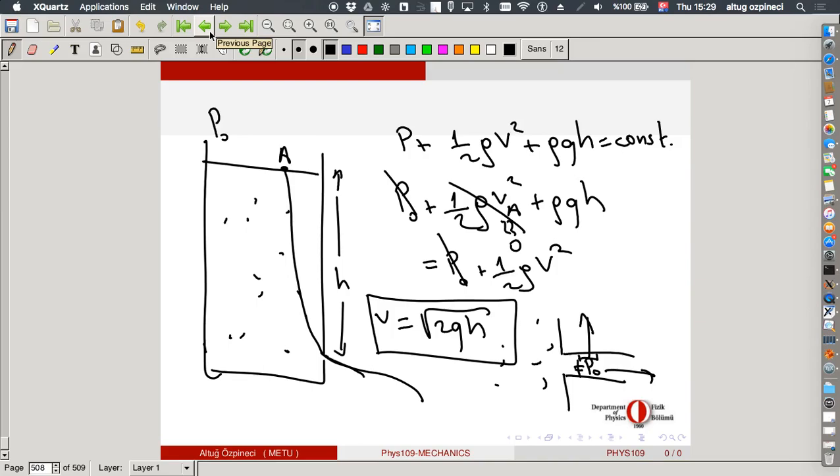Well, it will increase, but I don't think it will be linear. Since we are assuming that the hole is very small, only in the very near vicinity of this hole there will be any significant motion. Only in that very small region there will be some deviation from what we had calculated for a stationary fluid.